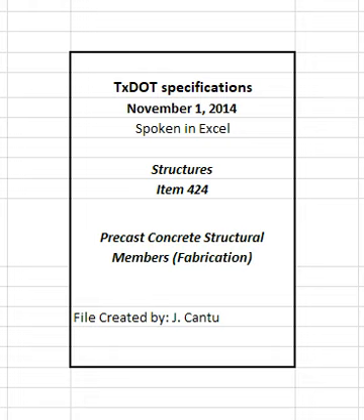4.2.2.2 Pre-tensioning. Pre-tension all strands to a uniform initial load between 5% and 25% of the final load unless otherwise approved. Apply the load within a tolerance of ±100 pounds per strand if the designated initial load is less than or equal to 10% of the final load, or ±200 pounds per strand if the designated initial load is greater than 10% of the final load. Measure the initial load with a calibrated dynamometer or other suitable equipment.